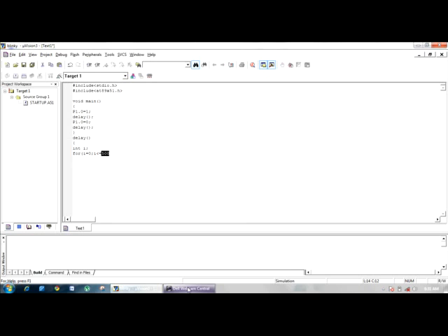When you reduce the numerical value, the delay becomes very brief, and you cannot even probably visualize the blinking of the LED. It will seem like a fast-flickering thing. So 500 is a nominal value. i plus plus. So inside the for loop I am giving just a semicolon indicating that it is a dummy statement. A dummy statement is very analogous to NOP, no operation, of the 8051 microcontroller's instruction set. So now I am closing the delay function.